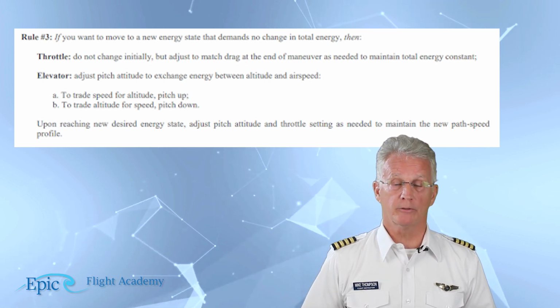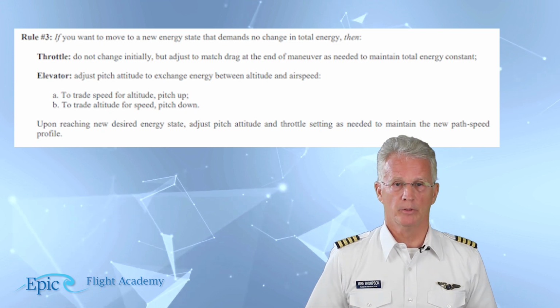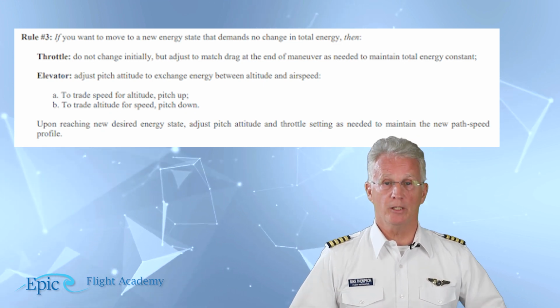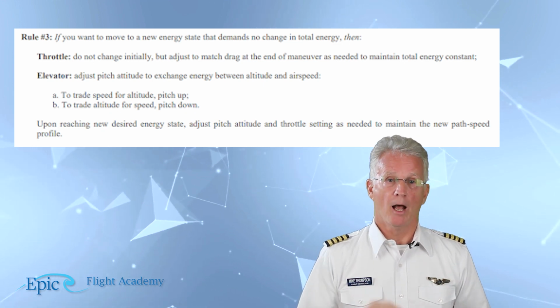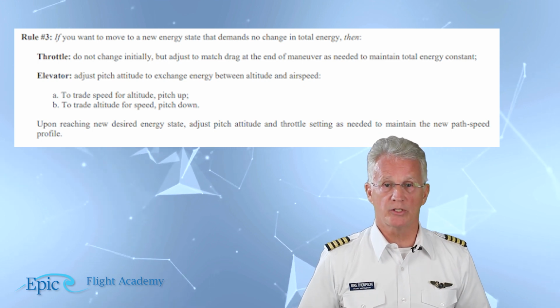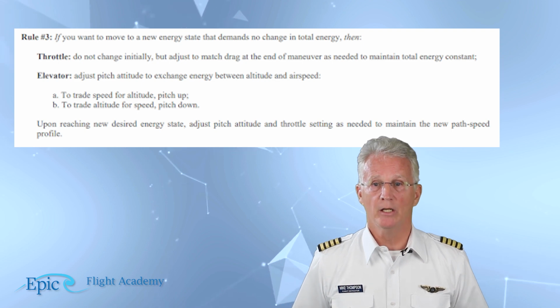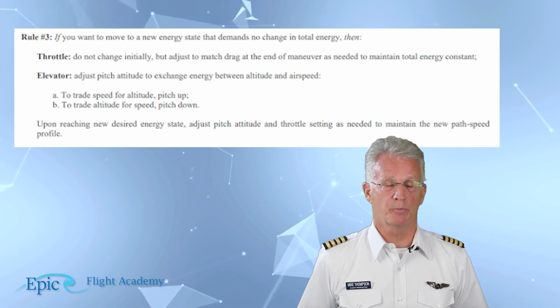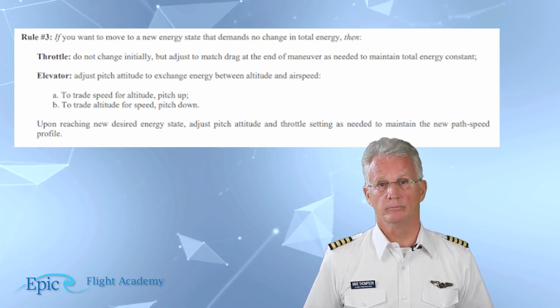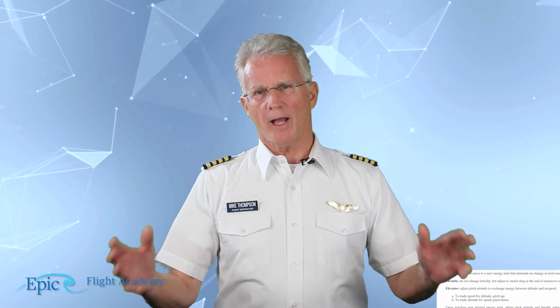To trade speed for altitude, pitch up. To trade altitude for speed, pitch down. Upon reaching your new desired energy state, adjust pitch attitude and throttle setting as needed to maintain the new path speed profile. Well, folks, this wraps up our review of energy management.